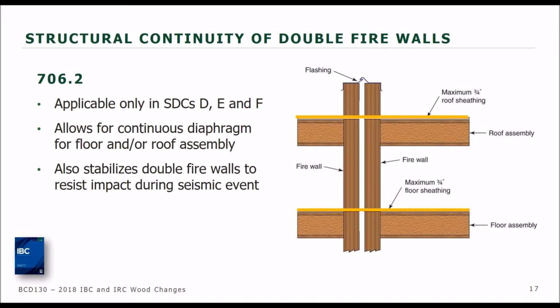Whereas the feeling was at 3/4 inch thickness, if you had a fire that was causing the failure, the probability of any material remaining after a substantial fire, and when I say material remaining is what would be left of the 3/4 inch sheathing, should not be significant enough to pull down the other side when it finally did fall away. It's gone. So that's why the maximum 3/4 inch was provided.